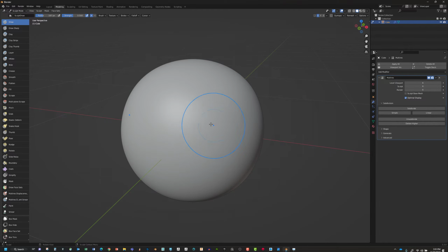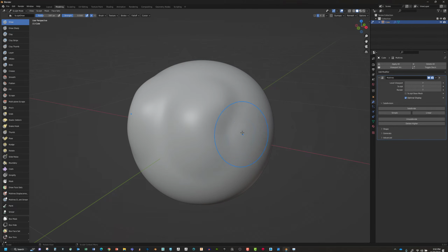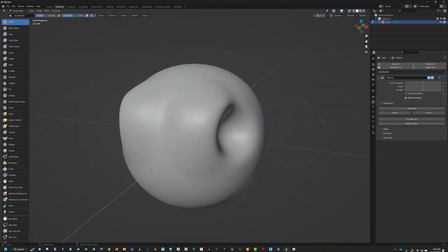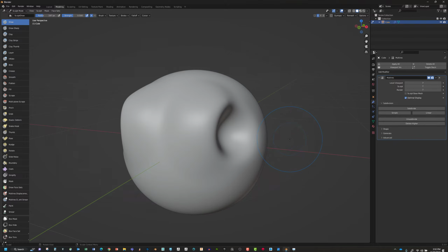You can see that even at the density we're working at, we can see the polygons. I would suggest at the very beginning, when you're just getting started, that you shouldn't have too much geometry. Anytime we're sculpting, we can subdivide and go even further. You saw that the levels when we're sculpting were different than the level in the viewport, so I just added it and made it exactly the same. Again, hold down Control while sculpting and that will dig in, sculpt and that'll raise the surface, and hold down Shift and we can smooth. These are pretty standard tools for any digital sculpting program. You're going to either add to the surface, subtract from it, or smooth it.